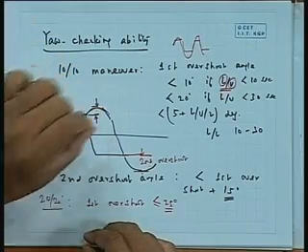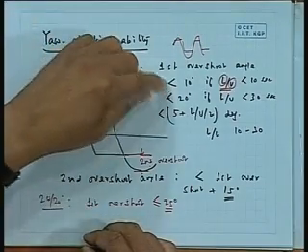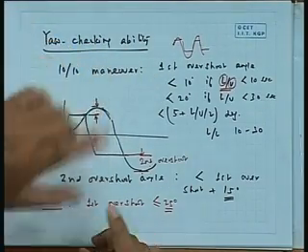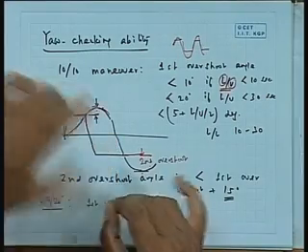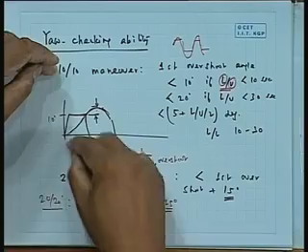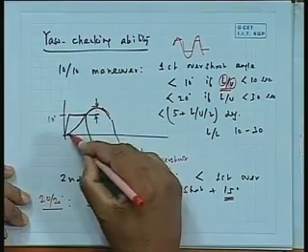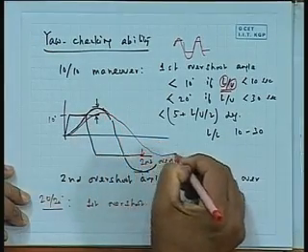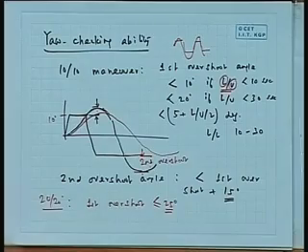Here they are concerned that it should not turn too much, the overshoot angles are to be less, which means whether the ship turns or not, it should be safe. The IMO's requirement is not that, supposing the ship turns very slowly, that is agreeable to IMO. IMO is not bothered if your ship is really sluggish and turns very slowly. They only want to make sure it does not turn so fast. You have not given such a big rudder that while turning it hits the bank on the side. That is what they are interested in.